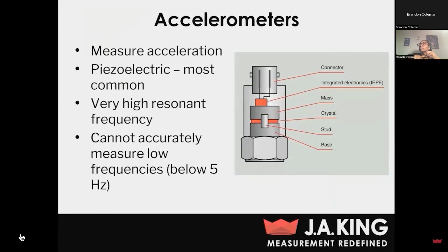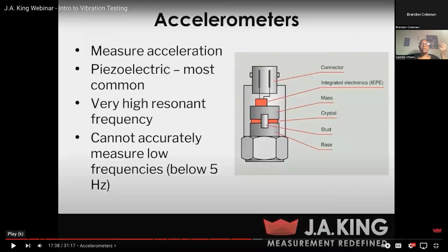So like I said, we tend to stick with piezoelectric accelerometers, but you really have to choose your accelerometer based on the actual test that you're performing. And this is something that the test labs have already worked out. So if you're running some packaging testing, transportation testing for your parts, and you're using a standard ASTM D4169 or an RC9, one of the ones listed in the AIAG spec or guideline, any of those specs, you go to any lab that's going to run any of those test sequences, they've already worked this out. This is just an FYI.